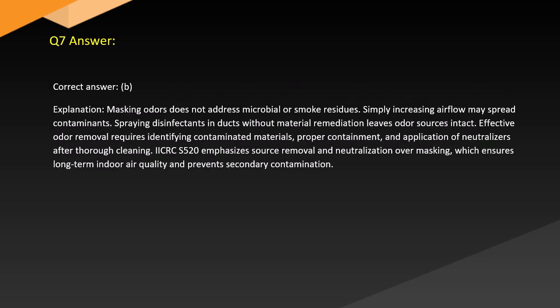Answer. Correct answer: B. Explanation. Masking odors does not address microbial or smoke residues. Simply increasing airflow may spread contaminants. Spraying disinfectants in ducts without material remediation leaves odor sources intact. Effective odor removal requires identifying contaminated materials, proper containment, and application of neutralizers after thorough cleaning. HRConquer emphasizes source removal and neutralization over masking, which ensures long-term indoor air quality and prevents secondary contamination.